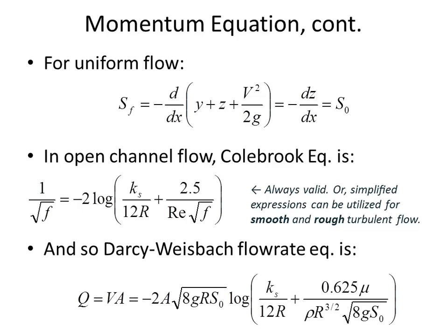And so you can find the flow rate using the Darcy-Weisbach equation, building in the expression for F. That doesn't look very fun to use. Is that R hydraulic radius? Yes. Dr. Wade, is that logarithm just assumed to be base 10? Base 10. Okay. I don't think we'll use this at all, but there it is.